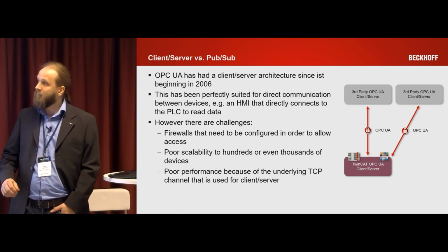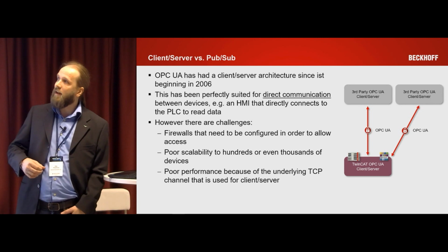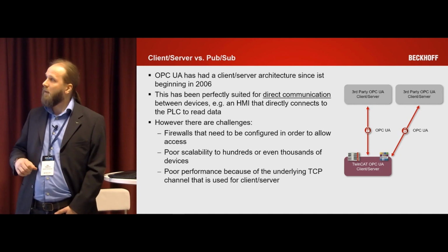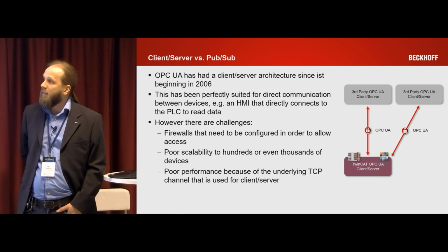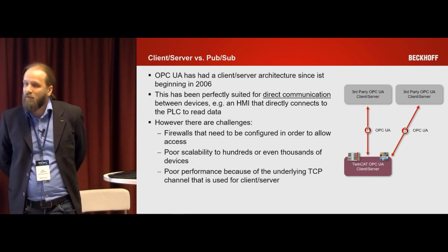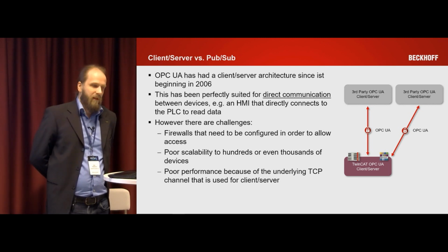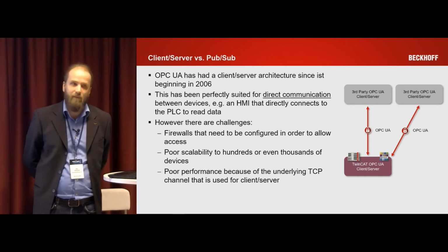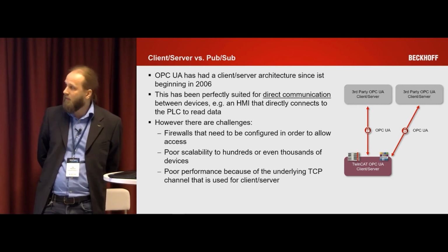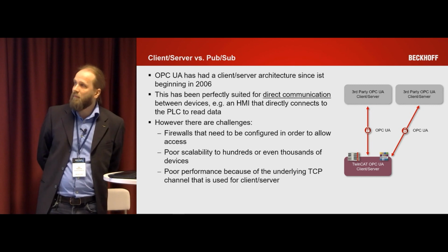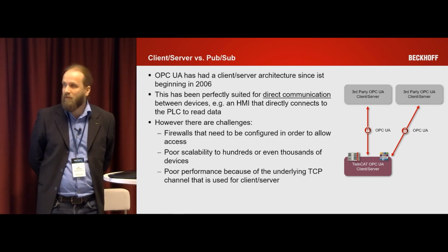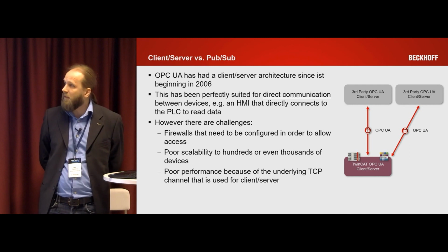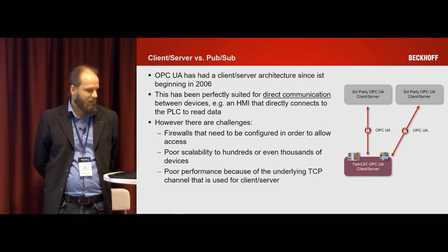Then commonly we have had this client-server architecture with our OPC UA products, and that's a good architecture and suits many cases, but the difference with the publisher and subscriber feature is that they are not competing with each other, but they are suitable for a little bit different network architectures and topologies and needs. So this is the client-server architecture you can see in this slide right now, and